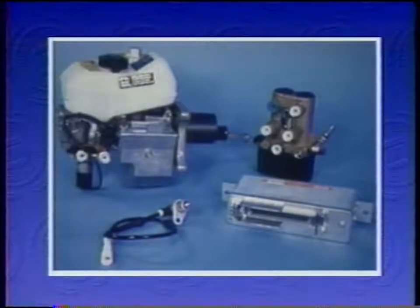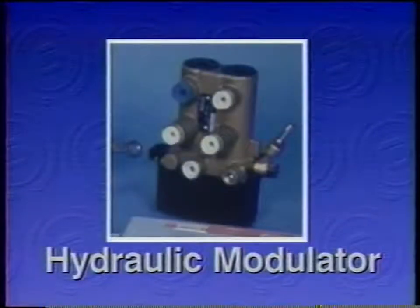Unlike Bosch 2, 2S, and 2U, the Bosch 3 ABS is a totally integrated anti-lock brake system. This means the master cylinder, hydraulic modulator, and high-pressure pump and accumulator are combined into a single unit. Bosch 3 is an integrated 4-channel system.